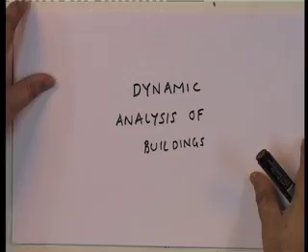And we showed that in buildings, you have a situation where you could do two-dimensional analysis or three-dimensional analysis, and we showed that two-dimensional analysis can be done when the center of mass and the center of stiffness of the building coincide with each other, and that there are no what are known as eccentricities in this structure.